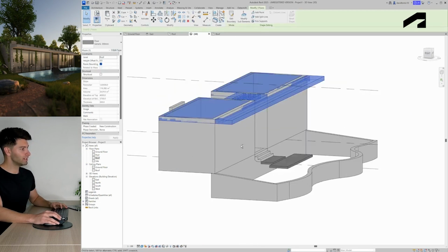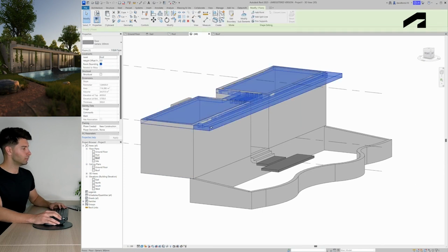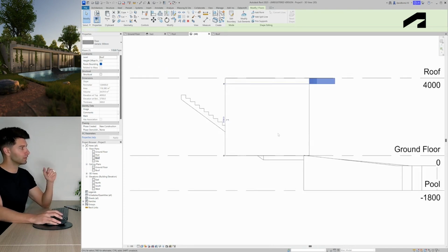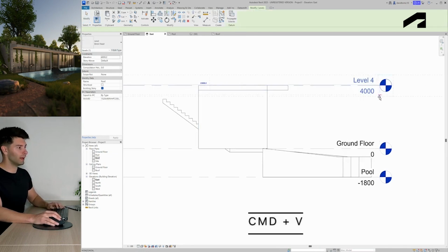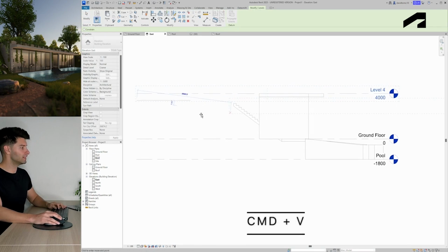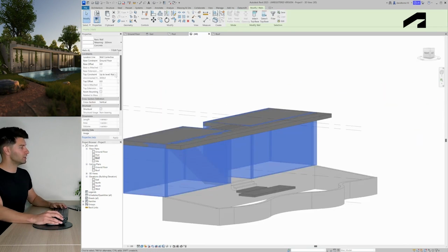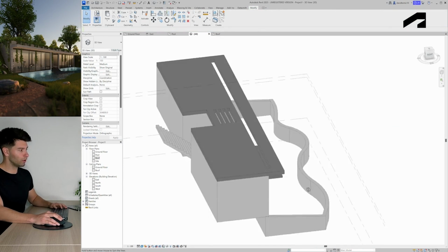So what we've created is this beautiful roof structure with our walls connected a little bit too high. Because our walls are connected directly to our roof structure and we haven't created a ceiling level, that's what's causing this issue here. So if I jump back into East, I can simply select, copy, paste, move 300mm down and call this my ceiling level. And then readjust my top constraint from roof to ceiling. And there we go. Automatically, it is adjusted all those walls down.